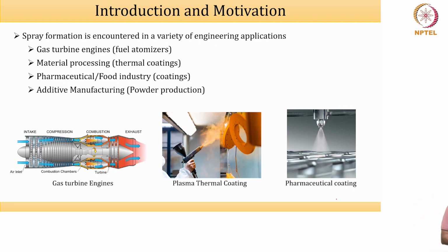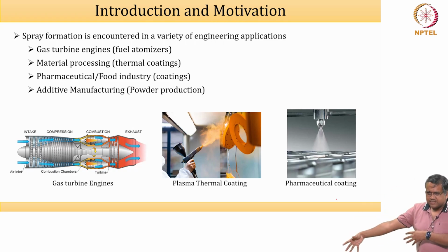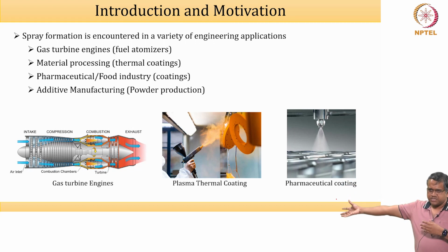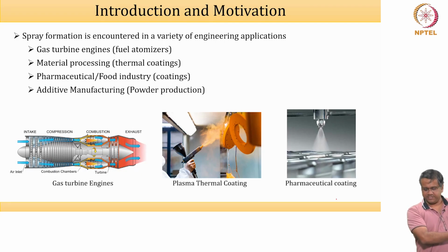Well, gas turbine engines are there. As we know, at the heart of the gas turbine is a combustor. The combustor uses sprays. Why are the sprays important? Because breakup of the sprays introduces the mist, which ultimately leads to mixing, and ultimately leads to what we call combustion stability and efficiency, right? So it adds that extra time scale of mixing in the whole mix of things, okay?